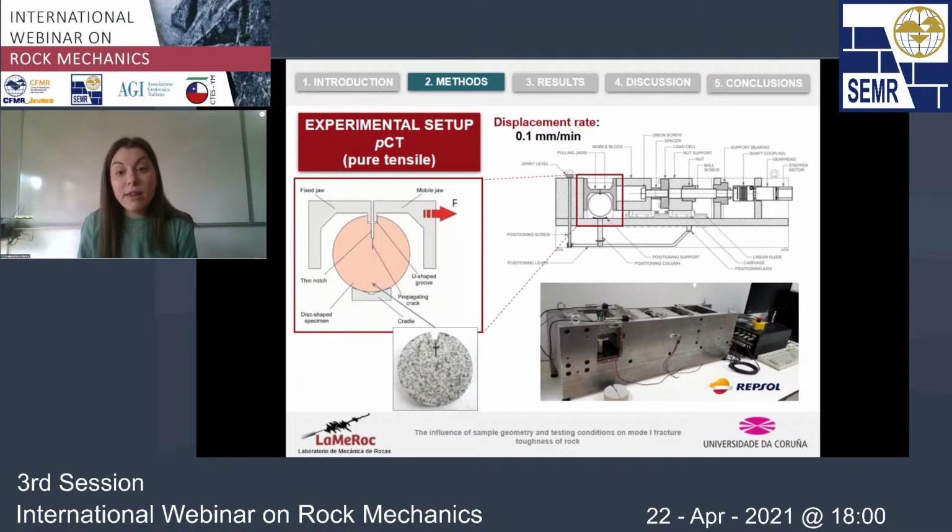We analyzed the results of the strains at the location, and we concluded that the device was over-dimensioned. And we also performed, thanks to some colleagues here at the group of structures, who helped us to create a numerical model of the device, a check with this model using the finite element method that the device was stiff.